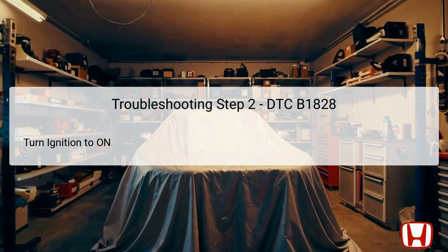In the second troubleshooting step for DTC B1828, turn the ignition switch to the lock position and then back to the on position. This action is critical as it resets the vehicle's electronic systems and allows for the proper functioning of the power seat controls.